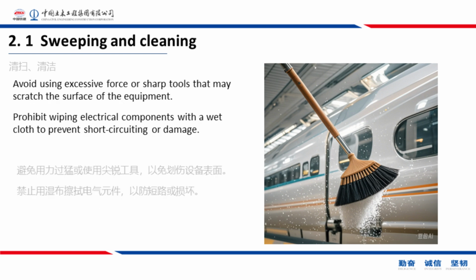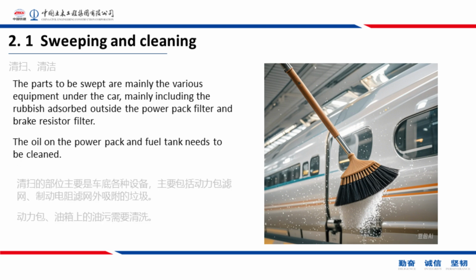PPT 16. 2.1 Sweeping and cleaning. Avoid using excessive force or sharp tools that may scratch the surface of the equipment. Prohibit wiping electrical components with a wet cloth to prevent short-circuiting or damage. PPT 17. 2.1 Sweeping and cleaning. The parts to be swept are mainly the various equipment under the car, mainly including the rubbish adsorbed outside the power pack filter and brake resistor filter. The oil on the power pack and fuel tank needs to be cleaned.